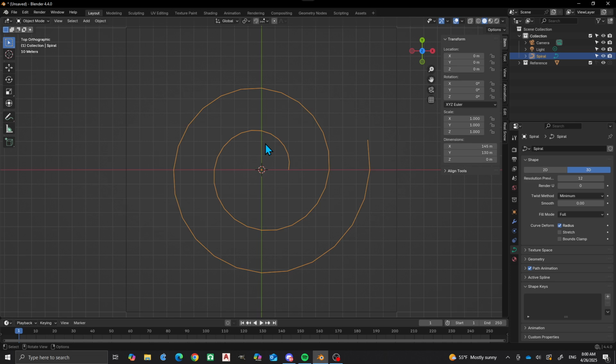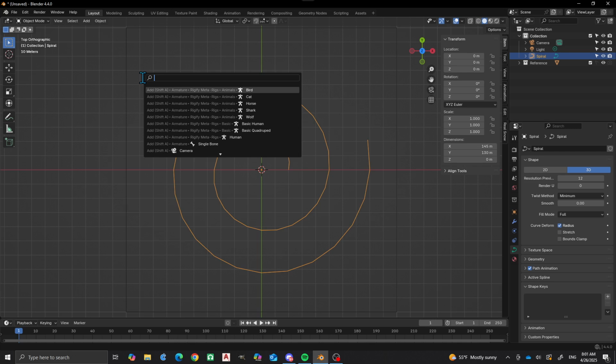So now the next thing that I want to do is that I have a couple of objects that I need to import from another scene. Rather than constructing the pieces that are going to go onto this articulated dragon, I decided to construct them prior and then just focus on how we're going to get this to follow on this print bed surface, okay? So to do that, I'm going to do F3 and I'm going to say append.